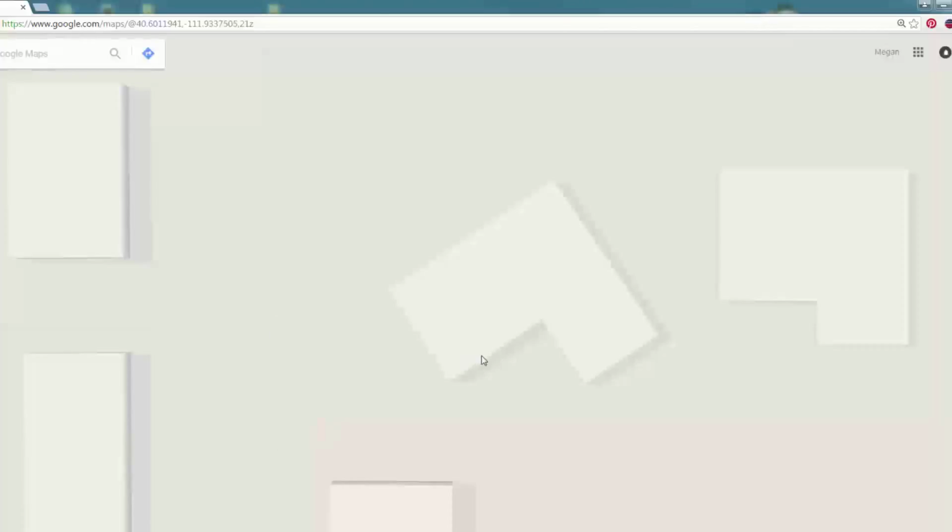Now the next thing will be measuring the house. I would recommend that we change to the next view before we do that, because although this looks like it would be super easy to measure, it gets a little bit tricky because these are simplified shapes. But one thing I do want to mention before we do that, it's tempting when you measure to think that you would just go from this corner to this corner to figure that out and have that measurement. The problem is it's going to be really difficult to calculate in the landscape what angle this is. So what I would do instead is make sure that when we measure, we're parallel to the house.